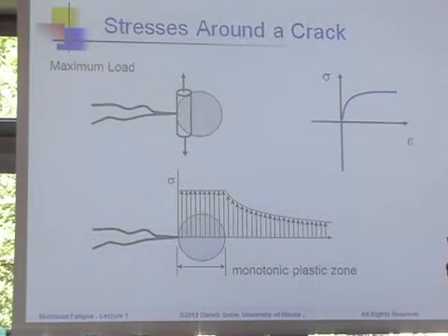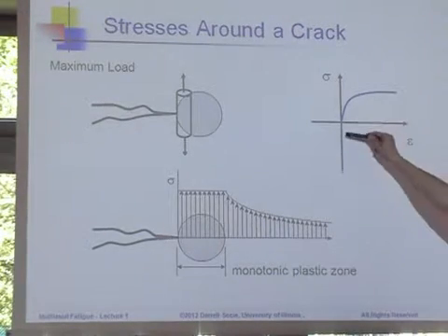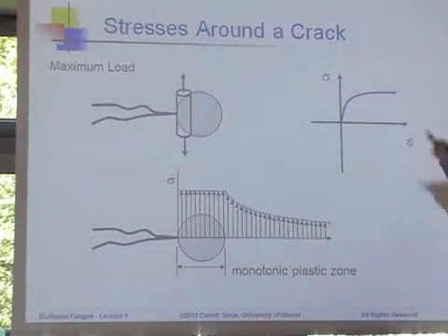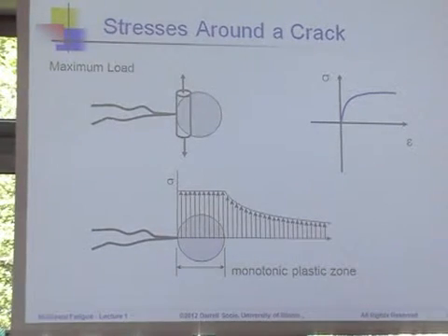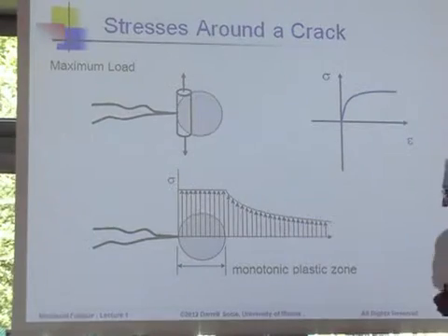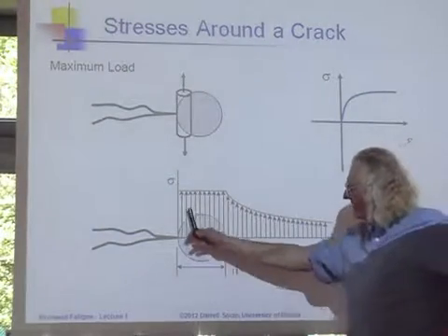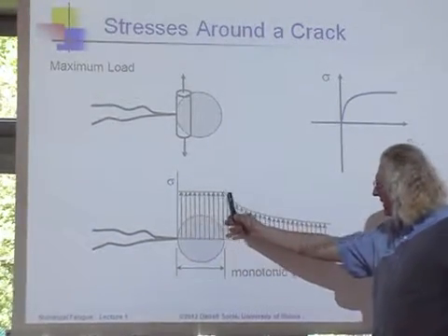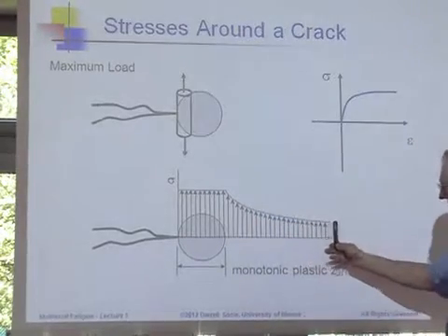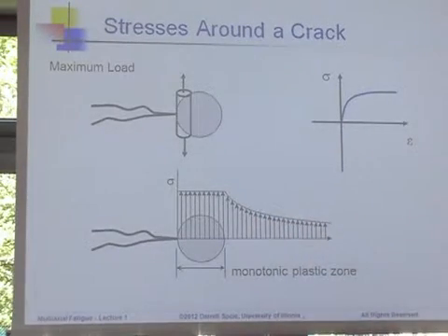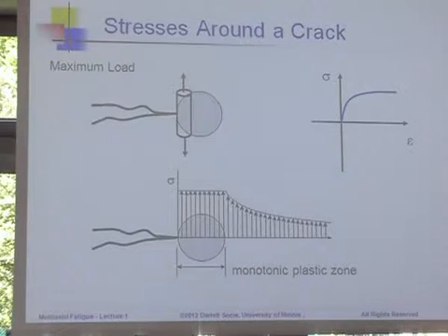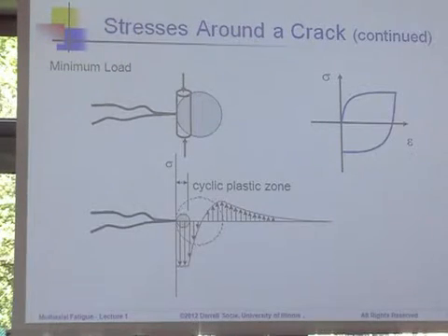And of course, as I pull this in tension, there will be a big plastic strain way out here someplace. And if I look at the entire stress field in front of the crack, I will have high stresses in this plastic zone. And then of course they will decrease and reach the average stress. And then of course when I unload this, something different will happen.